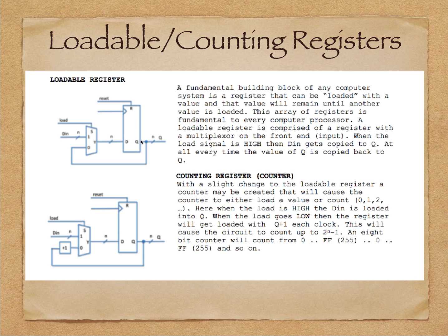What happens then is that the current contents of the register on Q will be presented back around to the D, so on every successive active edge of the clock, we are just refreshing the contents of our register, or we have a register that we can say is loaded. This is a very common structure. We'll use it again and again. It also sets the precedent for how we're going to be building our circuits.